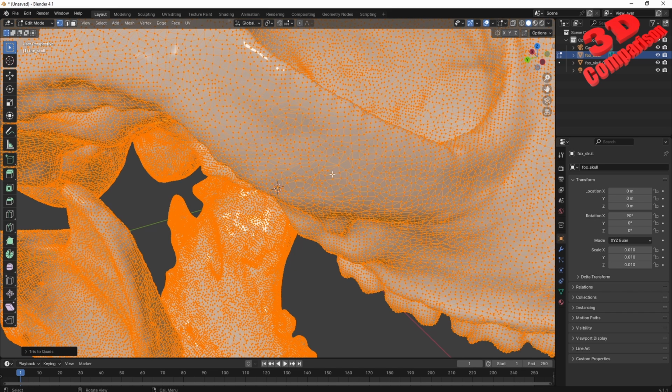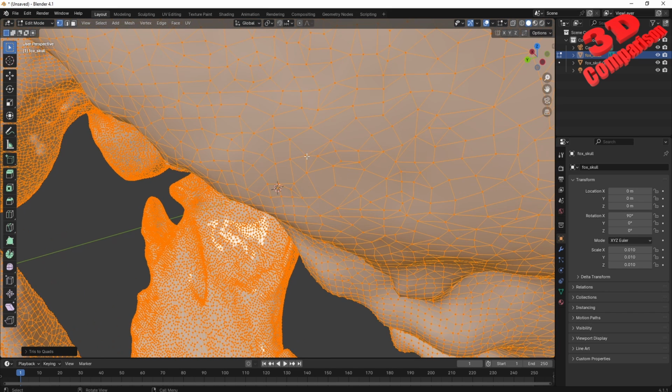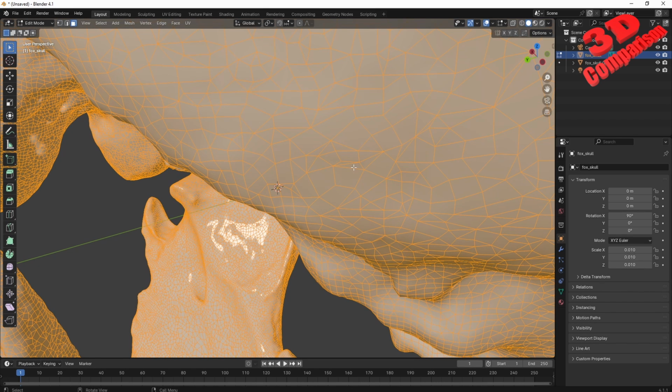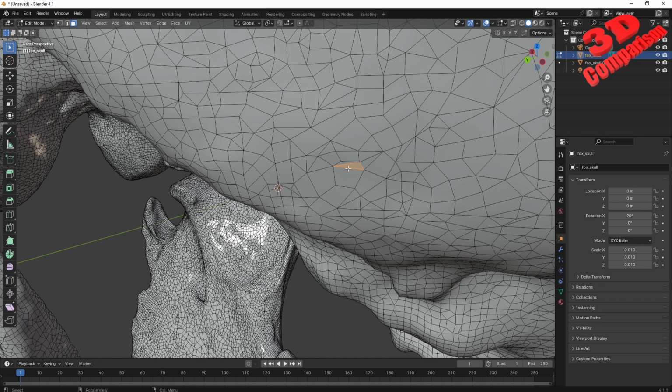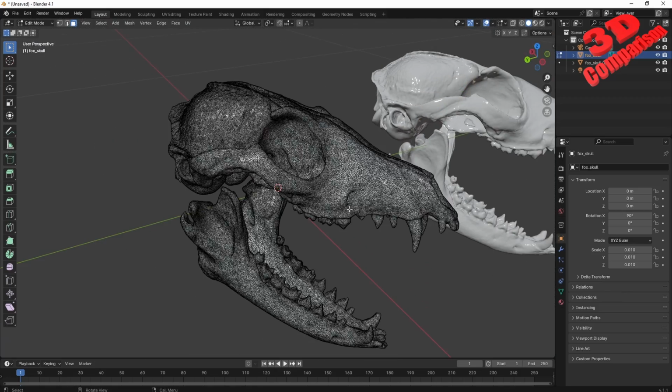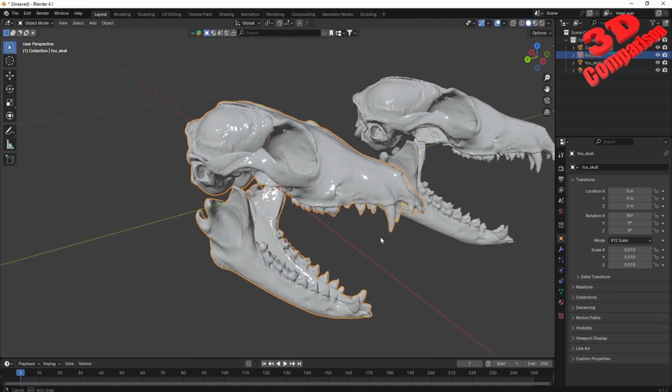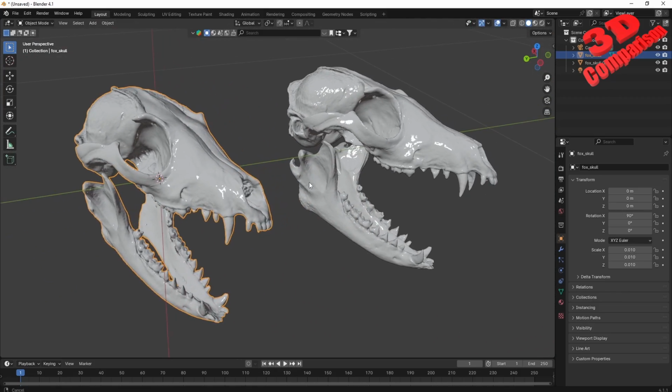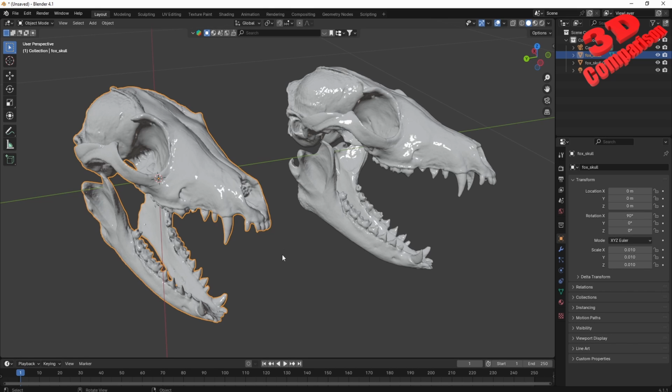As we can see, Blender will process the mesh, but we're still going to have a high amount of triangles over here that we can further join. So for example, those two triangles over here, I can select those, Alt+J, but this will take quite a lot of work, but we can do that remeshing with no plugins. Now, let's see how we can work with some plugins.